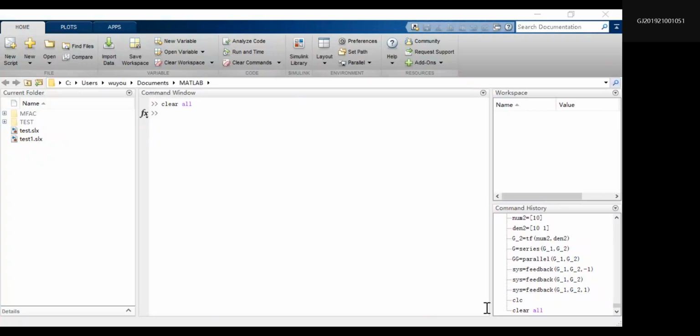And here, because we only talk about continuous systems, sample time is not a parameter we need, so we can just leave it 0. So it's okay. Okay, showing here, it says 10. What does 10 here mean? It means the simulation time is 10 seconds.